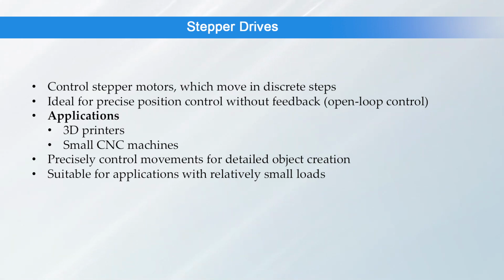Lastly, stepper drives control stepper motors which operate differently by moving in discrete steps. These features make them perfect for applications where we need precise control over position without feedback from the motor, that is open loop control, such as in 3D printers and small CNC machines where each movement must be precisely controlled to create detailed objects layer by layer as the load is relatively small.